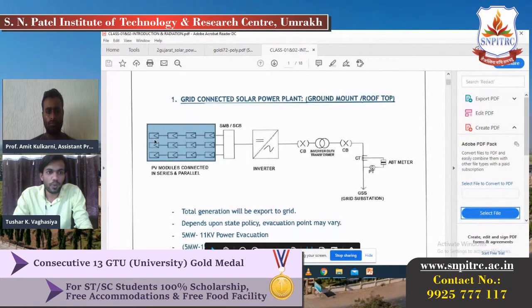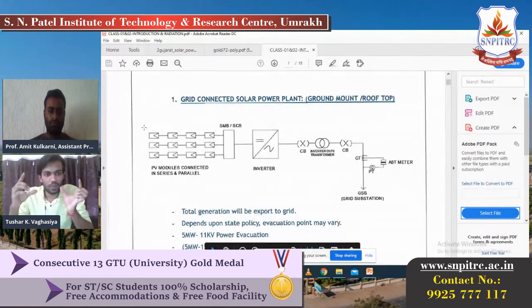If a number of modules are connected in series, it's called one string. How can we say that modules are connected in series or parallel? There are two terminals behind the module in the junction box. One is the positive terminal, and the second is the negative terminal. If the positive terminal is connected to the negative terminal, it's called a series connection, right? If positive is connected to positive and negative is connected with negative, it's called a parallel connection, right?